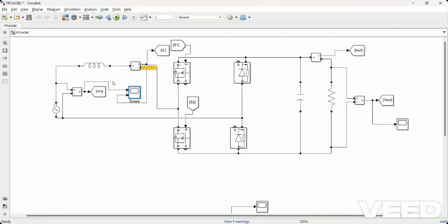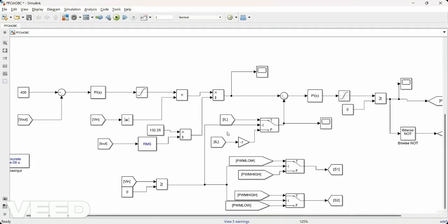You need to ensure, when the inductor is in continuous conduction mode, what should be your capacitance in the DC link, what is your actual load, and so on. Once you calculate the exact parameters, you get into this logic of operating it in the Totempole topology. So that's about it.